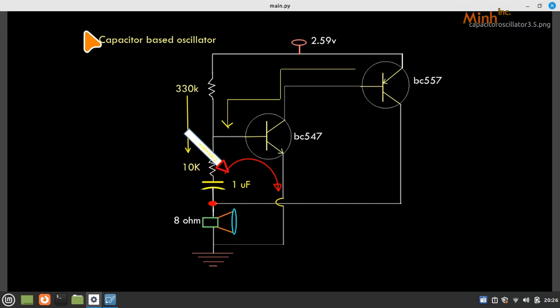Okay, so this makes a loop and it would discharge, making it forward bias, so the discharge would be very quick. It's a 10 kilo ohm resistance, and here 330k and whatever the resistance this path is showing. So we can calculate the parallel, plus 10k, and that much resistance it is getting when it is charging. So two paths are there, charging and discharge.